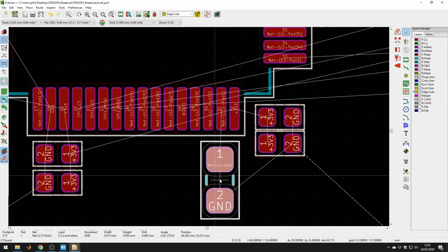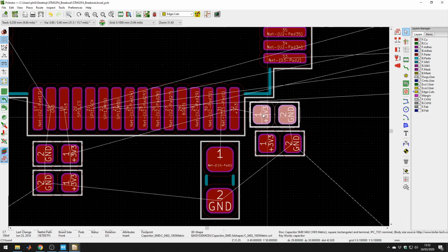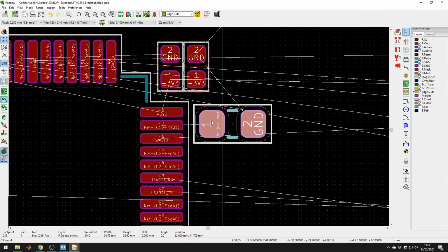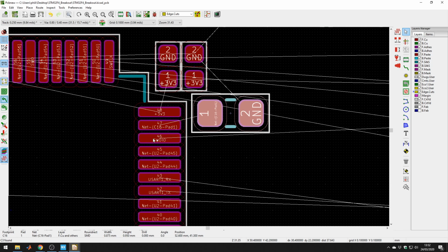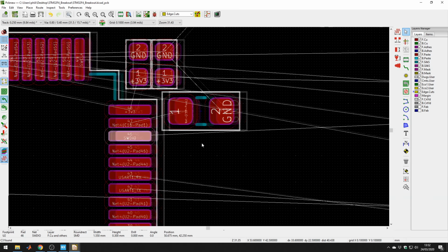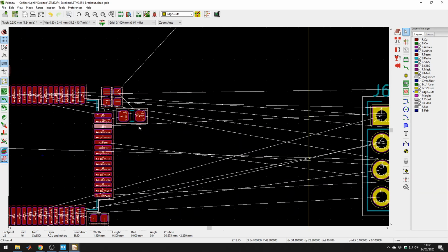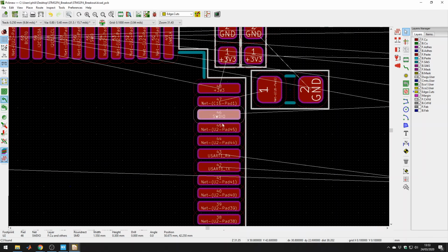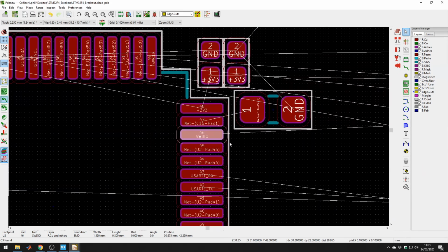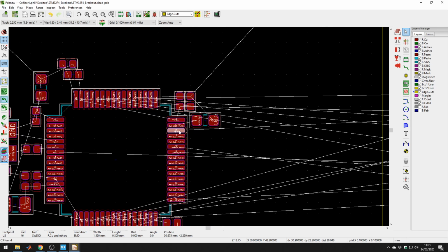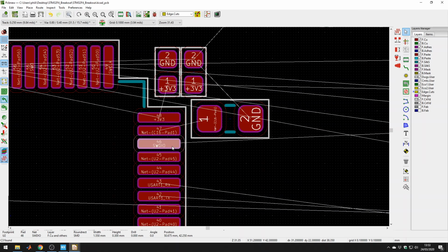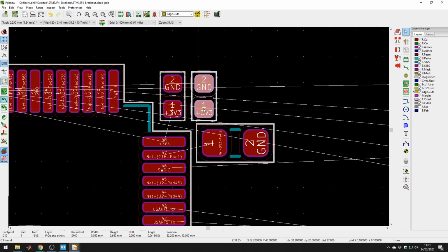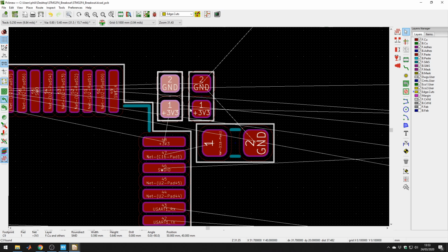So this is VCAP. Let's put it somewhere here. Decoupling capacitors. The second VCAP. Now this one I'm going to move slightly up, because this is the SWDIO trace right below it. This is more important, for example, than the N reset. N reset is just high or low, and it doesn't change very often. SWDIO changes a fair bit at a high frequency, and we don't want to use vias too much around high frequency traces, because that'll add inductance to the line. And of course, AC isn't a fan of inductors.